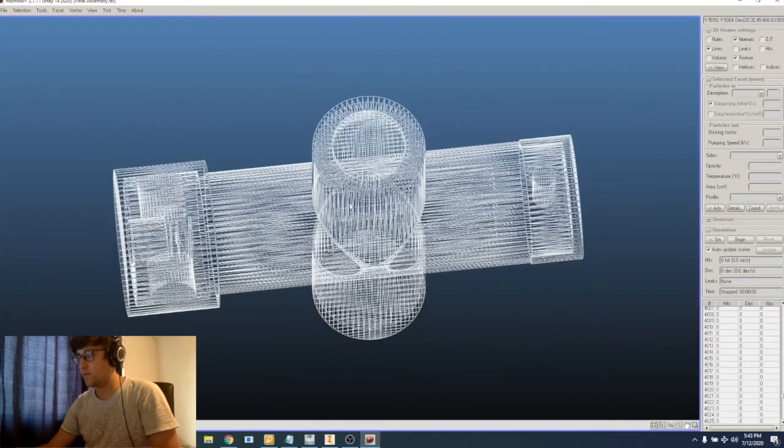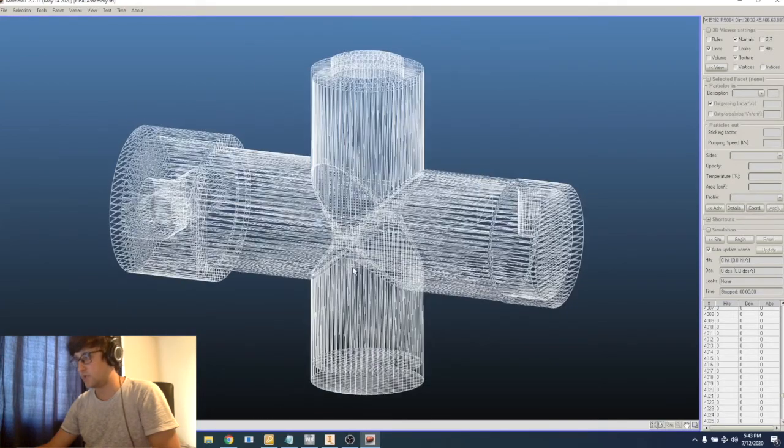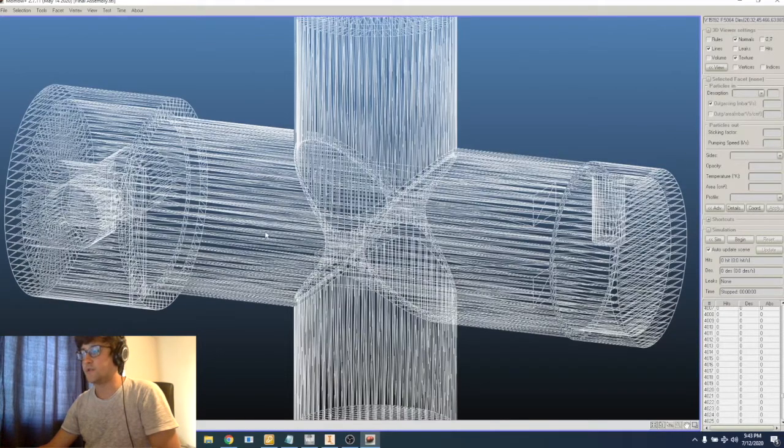When you first start simulating this, at every time step, it's going to calculate, based on all the particles and material properties that you put in, whether or not something is going to desorb or be absorbed. In the system, it's assuming molecular flow. None of the particles interact. The trajectories of the particles are pseudo-random. So if something is going to desorb from a wall, whether it's a new particle or one that had previously been desorbed, it'll calculate the probability. Its trajectory will be random.